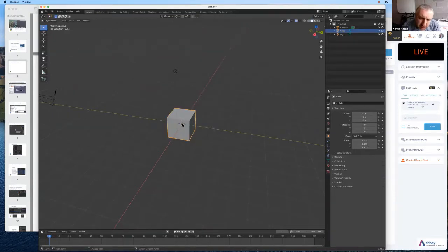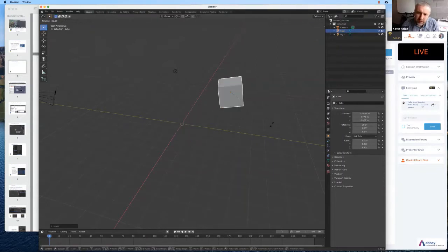So a very, very powerful way to move an object. Now you'll notice that at the middle of this cube, there is a little orange dot. That's the cube's origin. You can think of it as being a centroid or something like that. Now, if I press the R key, I can rotate about that object. So if I were to move over here, and then press R, and again, R X, Y, and Z, let's just rotate something like this. Now, if I want to move this relatively, I'm going to move it in the Z direction. It still moves in the global Z. Press the Z key again, I can move in the local Z, and the same for X and the same for Y.